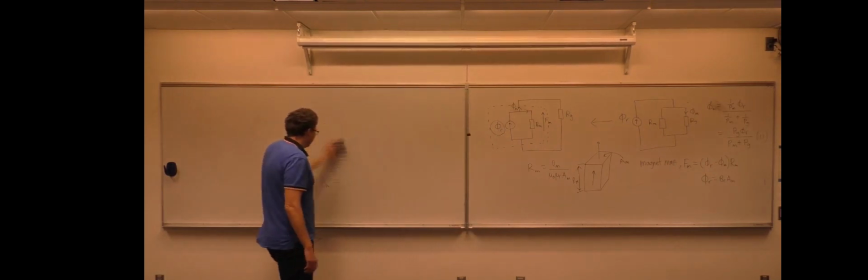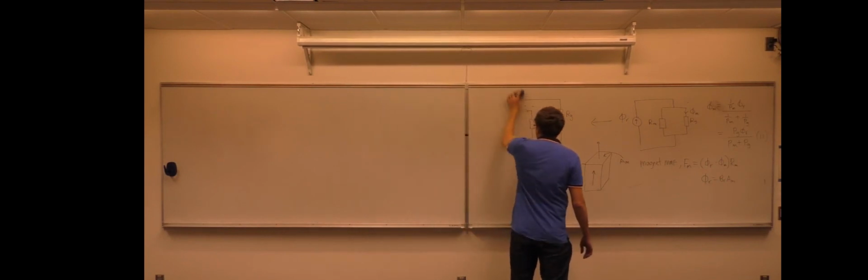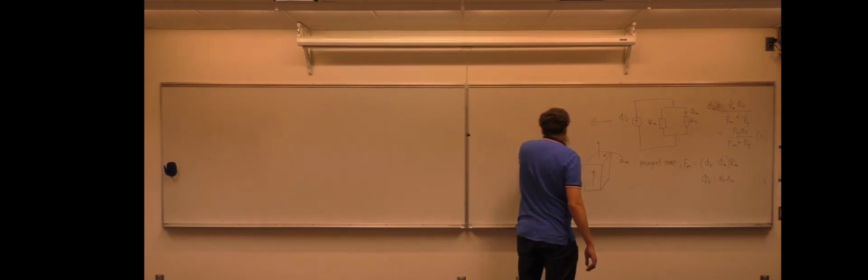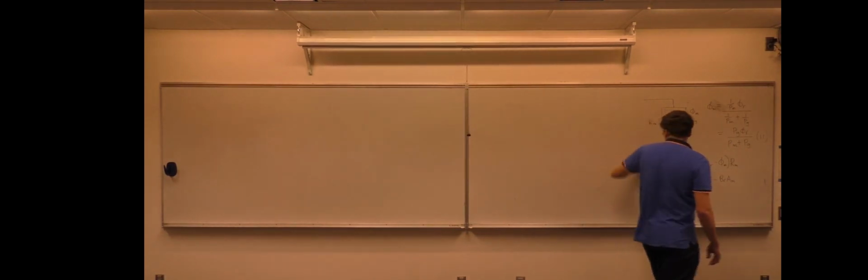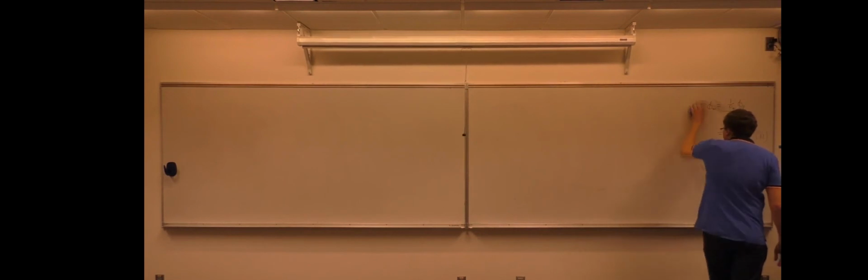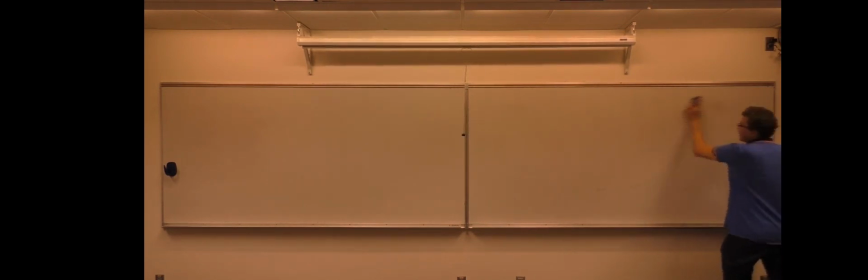You just have to think about the flow of the flux for one pole, and then figure out what each of the reluctance terms would be, and that allows you to then create a reluctance equivalent circuit model. So this is quite a general approach, even though it's on a specific machine.